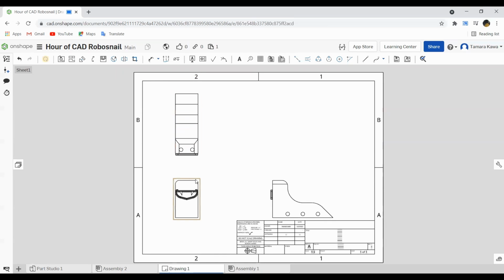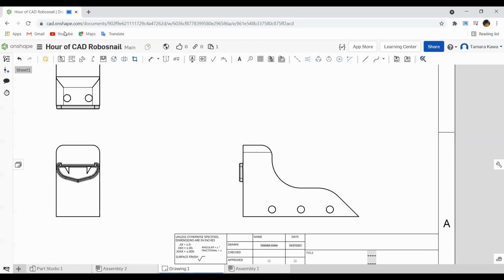Okay. So you'll notice that you have a top view, a front view, and a side view. For drawings, that's generally what you want to do. You want to have all 3 views so that you can give a general idea of what you're looking at. And if there's a certain side that isn't really identical to the other, you might even want to have more views than this. But the important thing with the drawing is that you can actually add annotations to demonstrate dimensions.